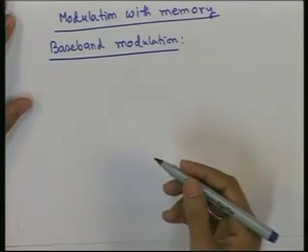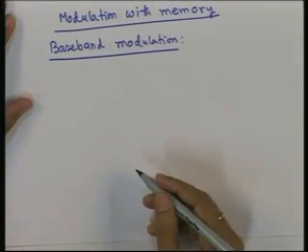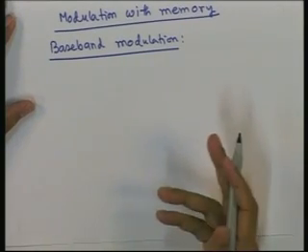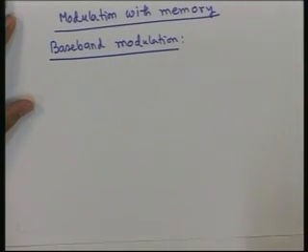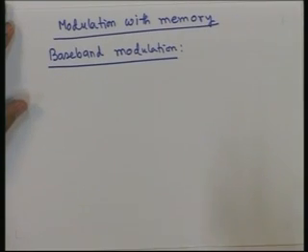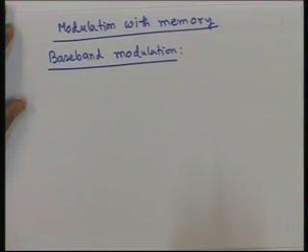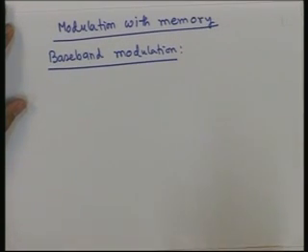So, we want to transmit 0, 1. Traditionally, we assign two levels for 1 and 0, and then transmit those voltage levels. It may be plus 5 volt for 1 and 0 volt for 0, but then the signal value is returning to 0 whenever there is a 0 bit that is to be transmitted.